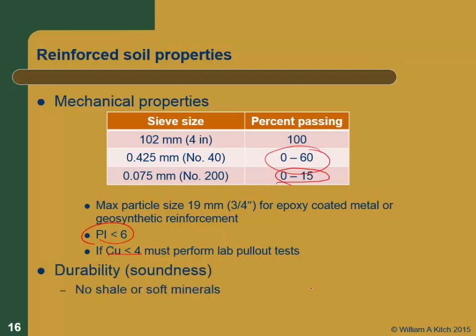So in durability, you don't put shale in there. No shale, no soft minerals. And you'd like the magnesium sulfate concentrations less than 30% and sodium sulfate concentrations less than 15%.